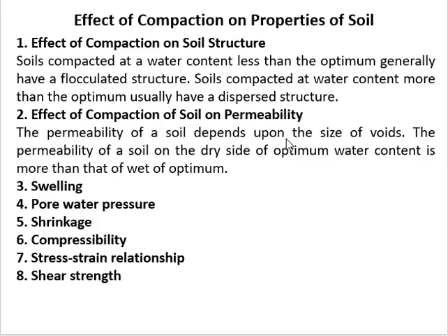Compressibility. The soil compacted dry of optimum is more compressible. Stress-strain relationship. The soil compacted dry of optimum will have more modulus of elasticity. Shear strength. The soil compacted dry of optimum will have more shear strength.